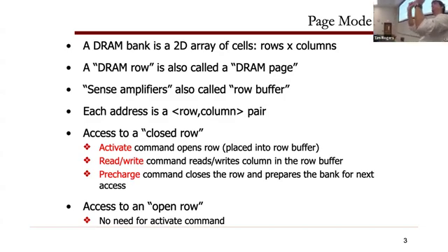The chip itself does not have enough wires coming out of it to read out the whole row, right? That would be a crazy design. It would just be too large. So the chip itself is going to be wire limited. Everything here is wire limited, because you've got wires running across the PCB, wires running across that PCB that's inside your DIMM. So you're going to have all this storage shrunk down into a small number of pins coming out of each IC or each bank. So I'm going to read out some quantum of each of those rows with specific commands.